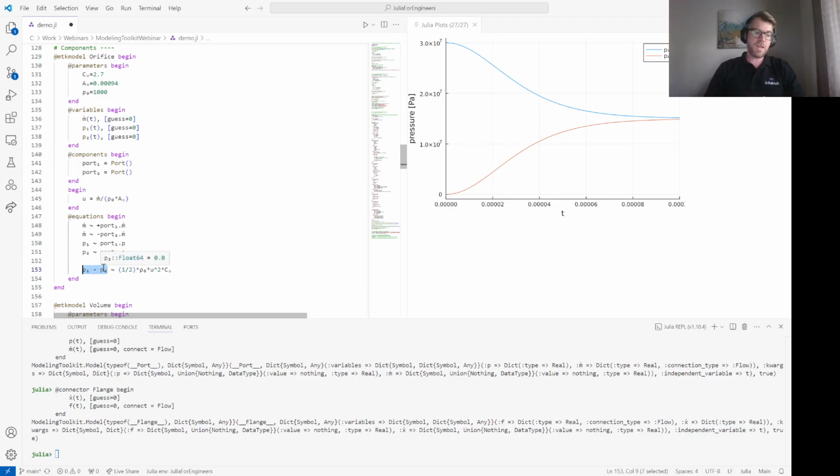And if this is negative, and the flow is going in the negative direction and the flow is negative, then you would expect the right-hand side to also be negative. But we can see that U is linearly related to mass flow m dot. That means if m dot is negative, U is negative. But if we square it, we get a positive value. And therefore, we'll have a negative on the left-hand side and a positive on the right-hand side, and that's no good.